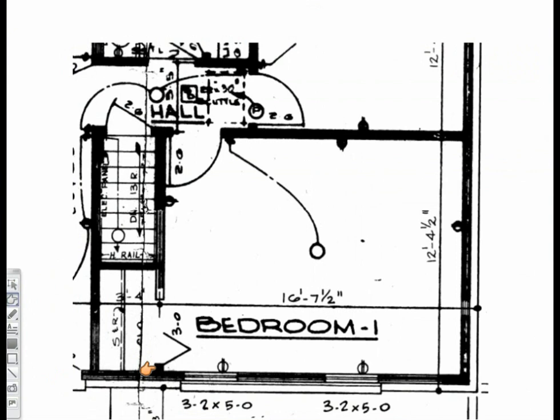The next interior wall you will create will be the vertical wall inside of bedroom 1. This wall is located 16 feet 7.5 inches from the exterior wall material to the center of the wall.